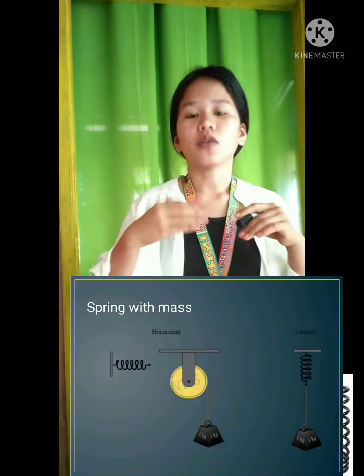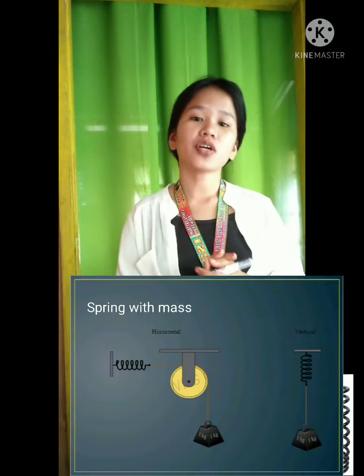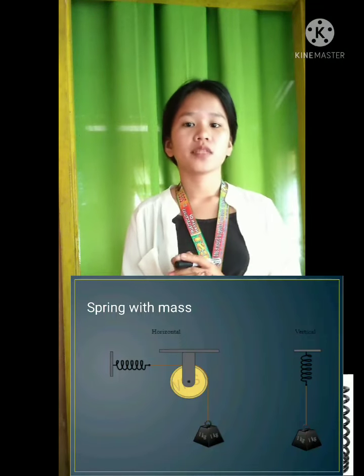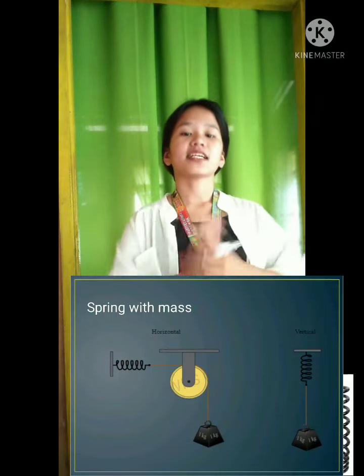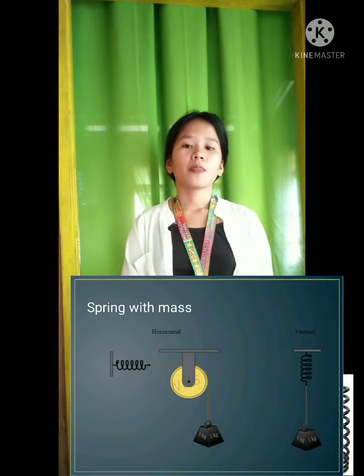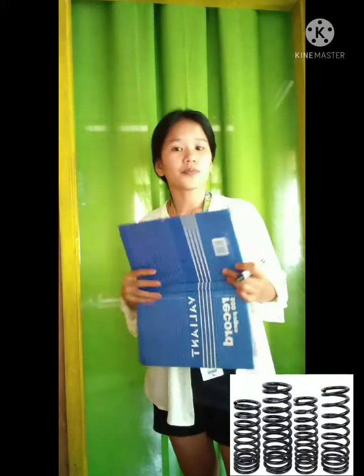The spring is supporting a total of 1.05 kilograms, which causes an extension of 1.05 kilograms times 9.81 meters per second squared, divided by 200 newtons per meter, which is the spring constant.